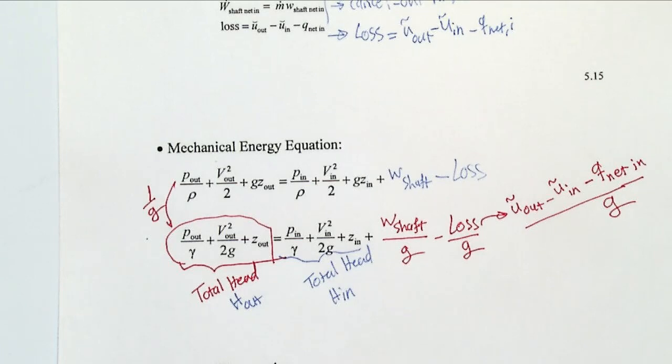That's why we assume it is a stream tube, because a stream tube could be extended to all the flow, like a pipe flow. If you assume there is no loss in these two terms, then total head is going to be conserved, and total head in and out should be equal, and that's your Bernoulli equation. So we extended the Bernoulli equation, but since Bernoulli is familiar to you, we keep that here.